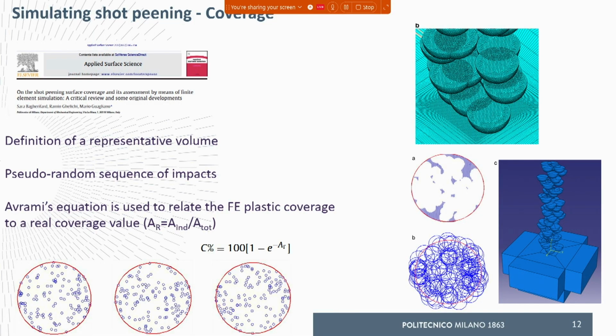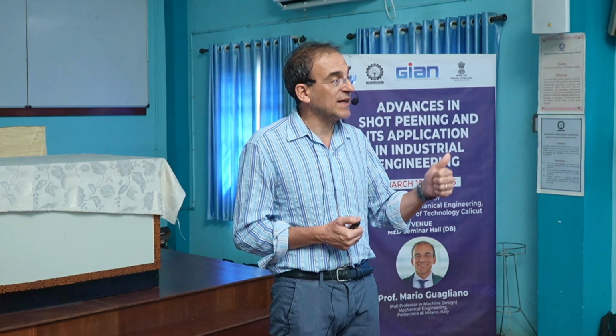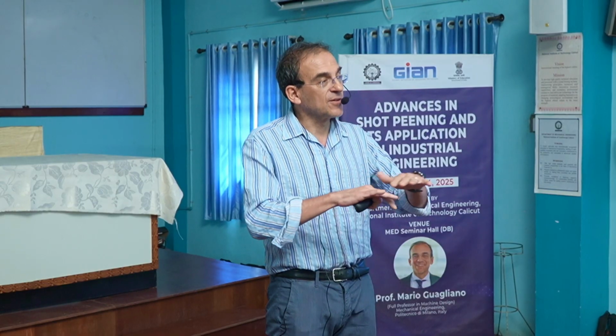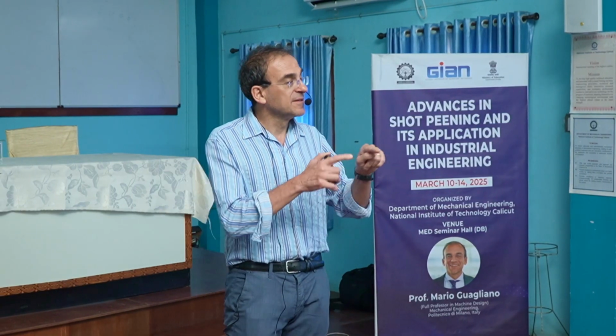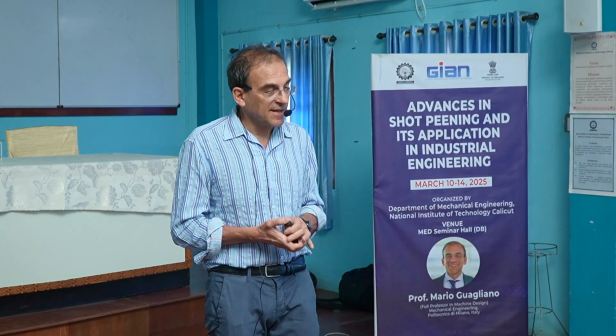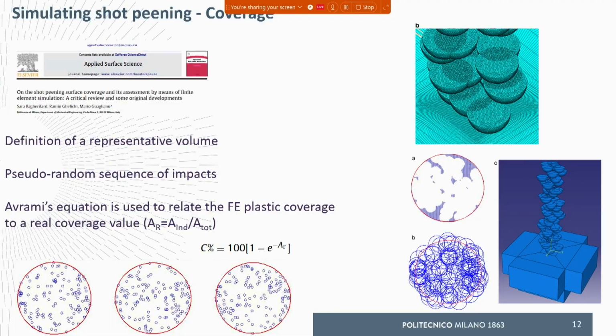And this is what we have for representing the coverage. Indeed, the coverage, we know, we have 100% coverage when the complete surface has been hit by at least one shot. When we look at the complete surface, we cannot notice any unpeened portion of material. And we developed this basic unit, let's say. Here, the impacts are confined in the central part of the model.